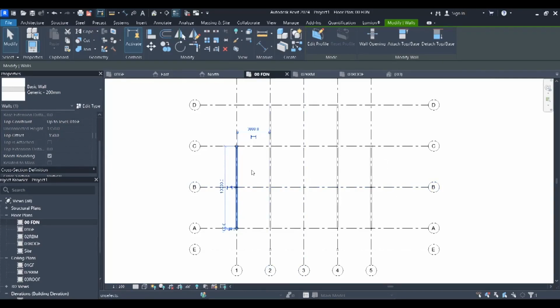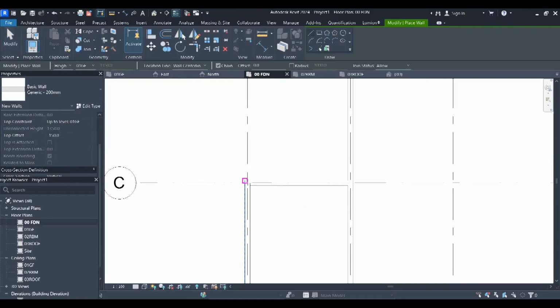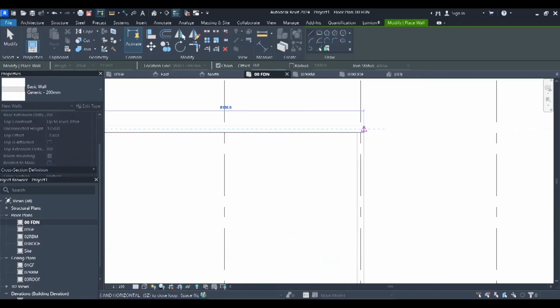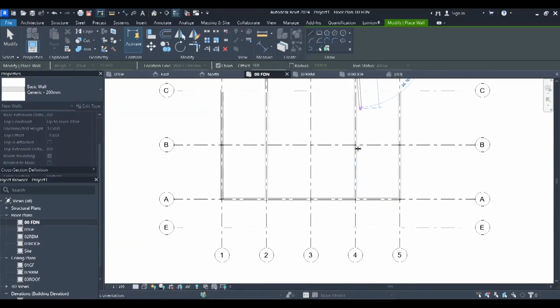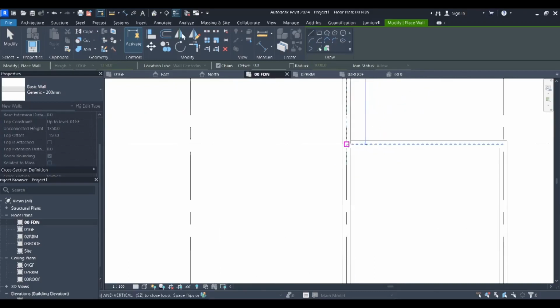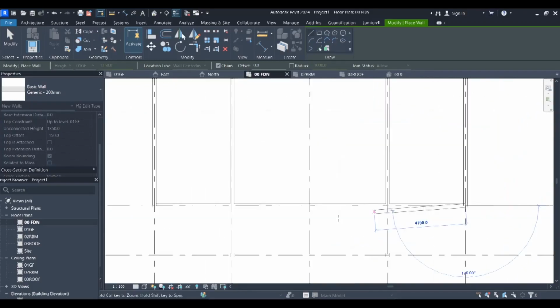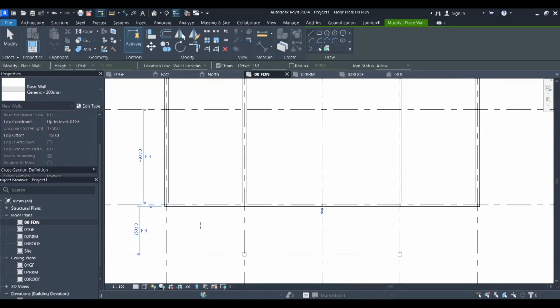So if I want to place foundation walls, I said instead of continuing, I can create similar. You select your wall. And then let me assume my foundation is at the edges. The other ones, which is not practical, let me say are load bearing and not load bearing walls. So the wall I have placed there will have the same properties.